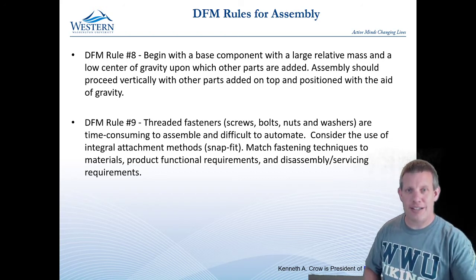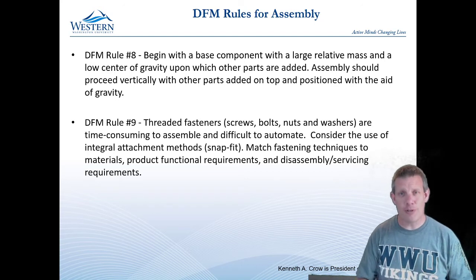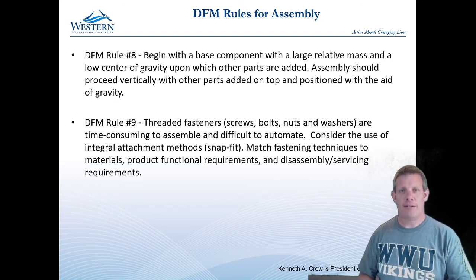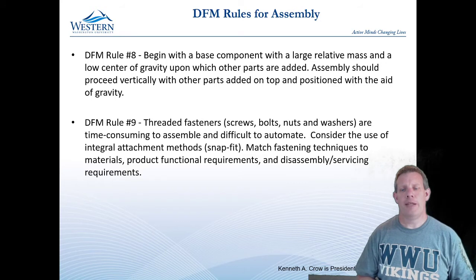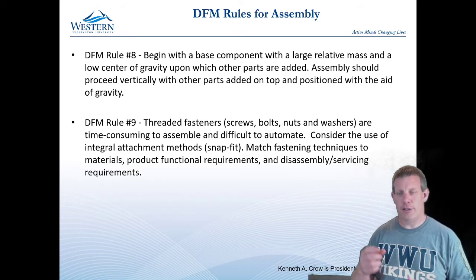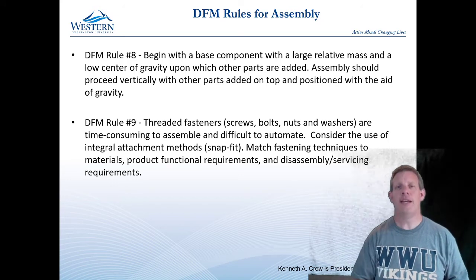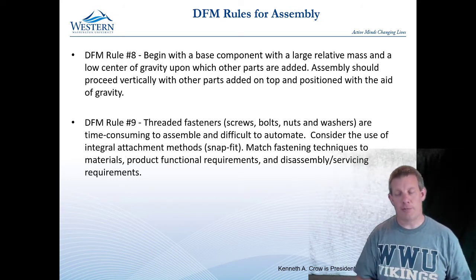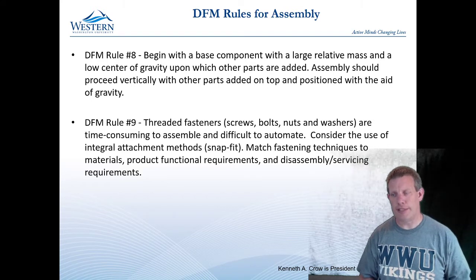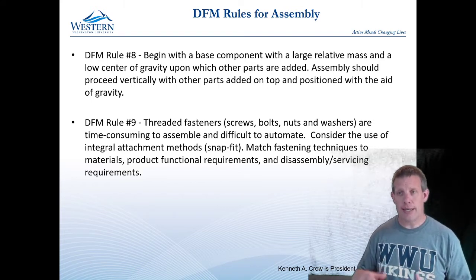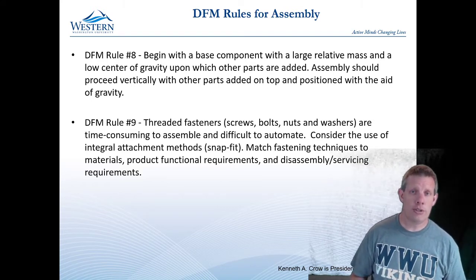And then for the fastener to have full strength, you want to have at least 1.5 to 3 threads sticking out on the other side. And so those are kind of wasted threads, but they're important to know that you've put the screw through far enough, and you have to have enough length that you're supporting across multiple threads. So that you are spreading the load across multiple threads. So anyway, all that to say, threads are slow.